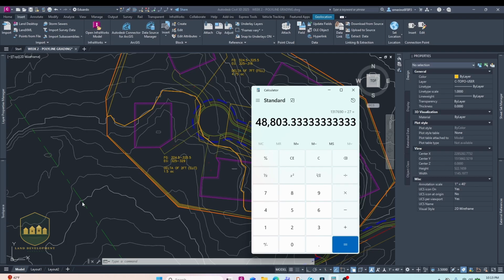So think about how many trucks we'll need to get 48,000 cubic yards. You just need a lot of dirt. We need to bring it. The only way you can bring it is with trucks. So take a moment, think about it. How many trucks will you need? Okay, here's the answer. One truck can carry 12 cubic yards of dirt, meaning we will need 4,000 trucks to make this thing work.